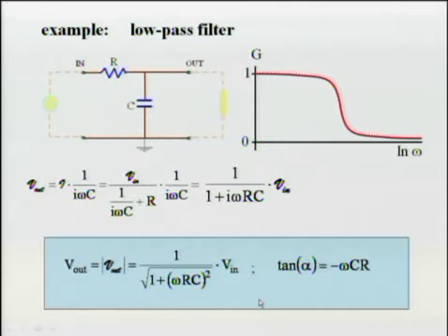At high frequency, by the way, notice that there is a phase shift, because at high frequencies this expression goes to -infinity, and the tangent of -infinity is -π/2. All right, so we will have a phase shift between the signals over there, but we don't care about it because it is not transmitted anyway. So for the operation of a low pass filter, we don't care about it.